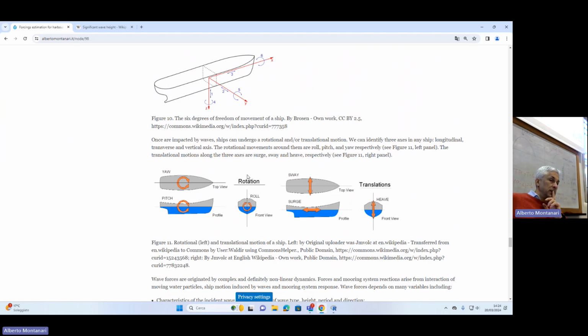Okay. We will see that, you may remember that I think we mentioned it when we talk about wind forces. We assume that wind forces don't cause a movement along the vertical axis. They don't cause heave. And the rotation is only induced in terms of yaw. When we have wind forcing, we assume that. For the wave forcing, of course, we have to consider heave.